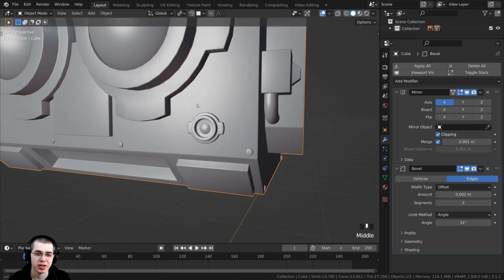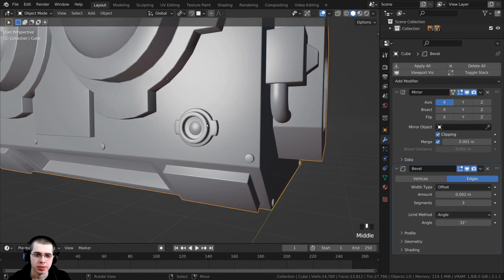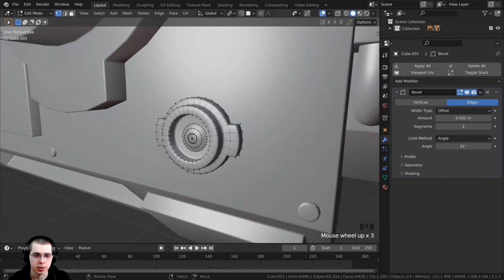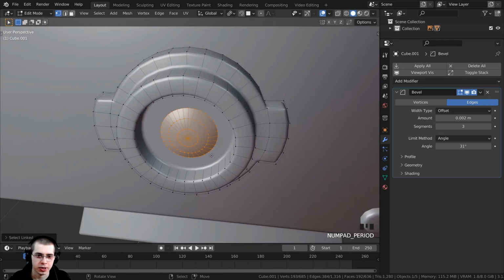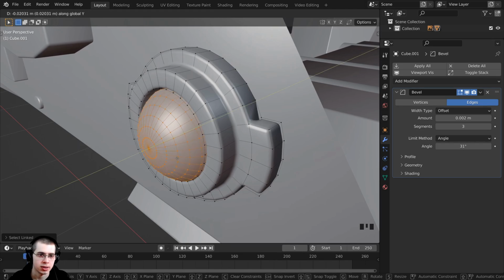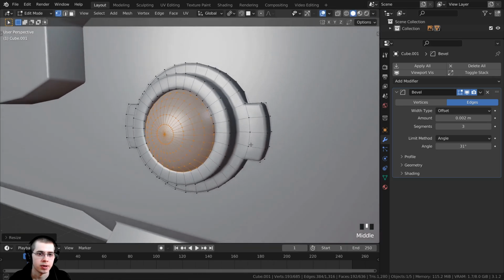And then I don't quite know what happened here, but you can see that circle there is way far back. So I'm just going to select this object again. Let's press Tab to go into edit mode. Hover your mouse over this object, and I'm going to press L to select the linked vertices, and then I can press period on the numpad to zoom into it. So I can press G to grab, and then let's bring this forward on the Y-axis. Just bring that forward, and then I can also press S to scale that up. All right, there we go.